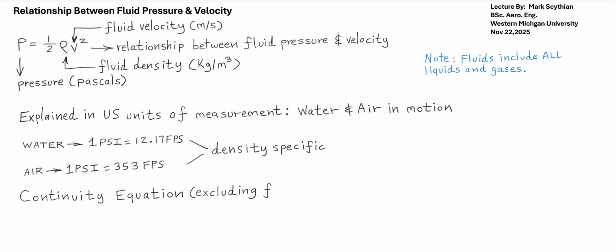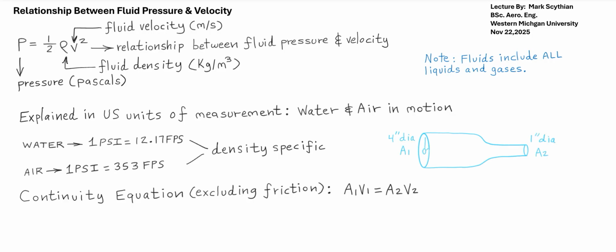So next we have to add the continuity equation, and this then completes the total relationship understanding. So if we had a duct with a compressor fan ingesting airflow and compressing it through the duct greater than atmospheric pressure, assuming the fan has the power to do so, we would incur obviously a backing pressure. This sort of pressure is known as static pressure, but the pressure while the fluid, or in this case air, is moving is known as the dynamic pressure.